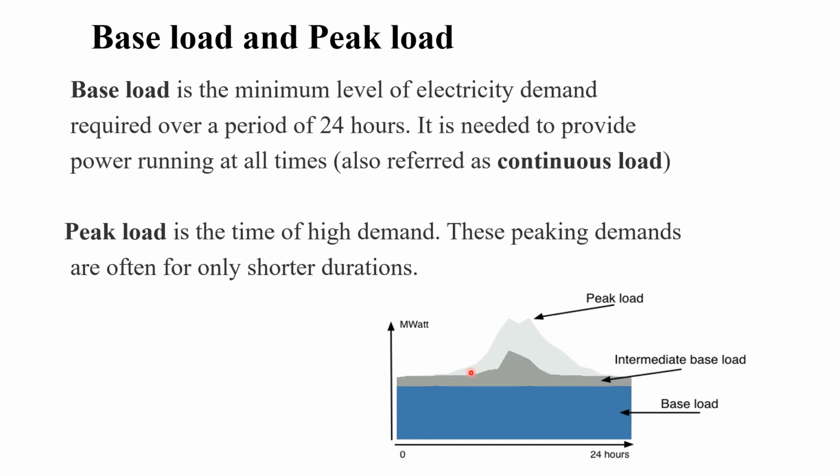In the load curve we already discussed, in the morning from 6 a.m. to 10 or 11 a.m. the load will be maximum, then it drastically decreases, and finally after 6 p.m. it increases up to 10 or 11 p.m. During those peak periods, some of the loads will be there.